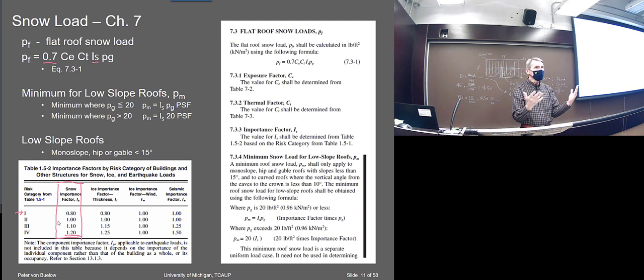Well, they had rated that shed like you would a garage, right? So it would be importance category 1. Well, making it importance category 1, in a 50-year snow, it had a good chance of failing, and it did. Every single utility vehicle in East Tennessee was trapped under this shed that collapsed on them.